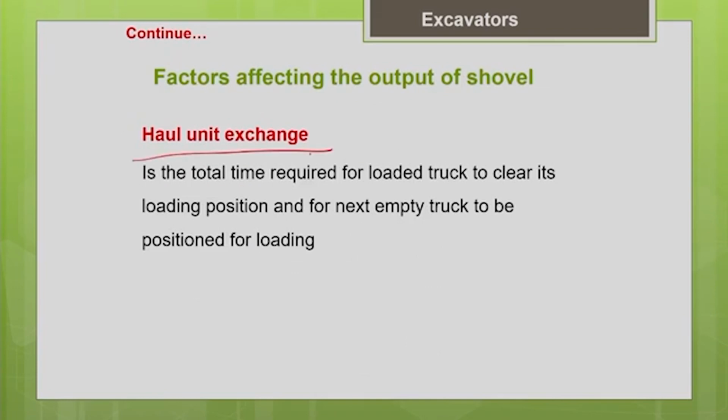Okay. Another important factor is haul unit exchange time. That means the time needed for the loaded truck to leave its position and for a new truck, that is an empty truck, to take the position. That is called the haul unit exchange time. Okay. So, this is also going to affect the productivity.